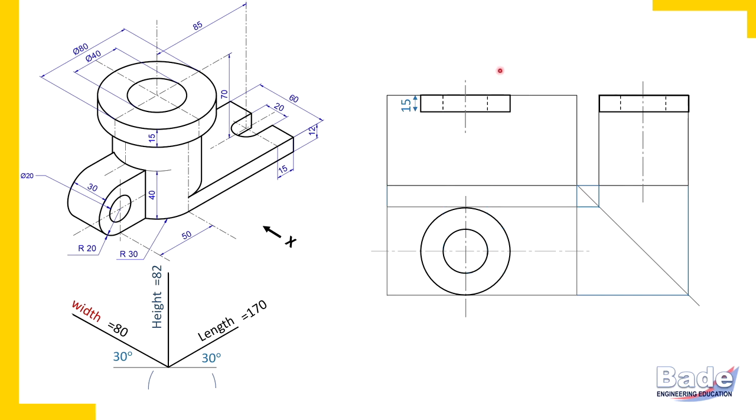Now let's proceed. Watch this dotted circle, what it is. Of course it is the cylinder which is under this disc, and it is hidden in the top view, and that is why it is a dotted circle. How are you going to draw the views of this cylinder?